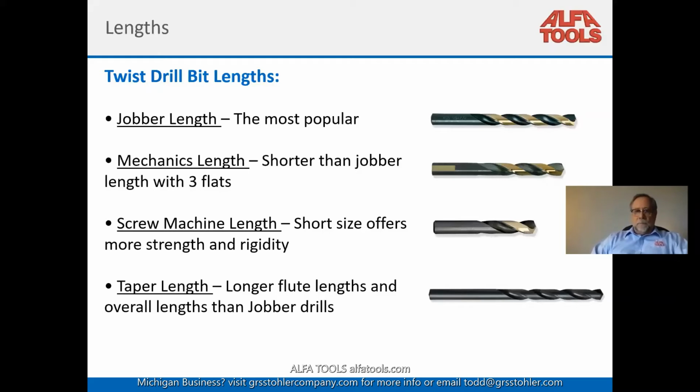I heard a fun fact here a few years ago that 80% of the holes out on the market can be drilled with a screw machine length. Why does everybody buy the jobber? I don't know. They think they're getting more for the money. And in some cases, obviously you can go deeper with a jobber drill.